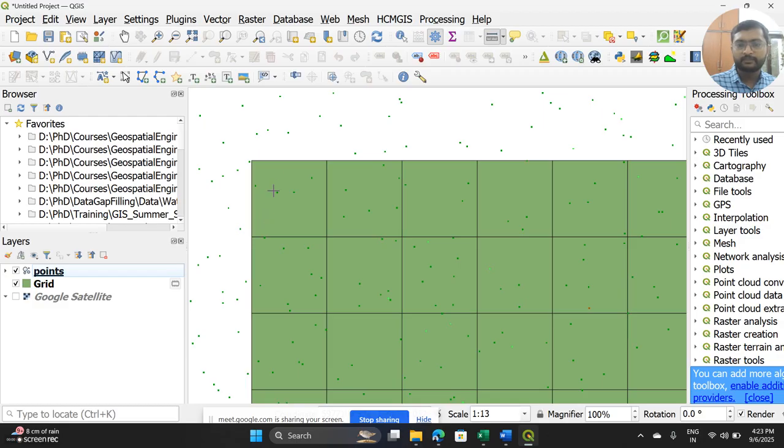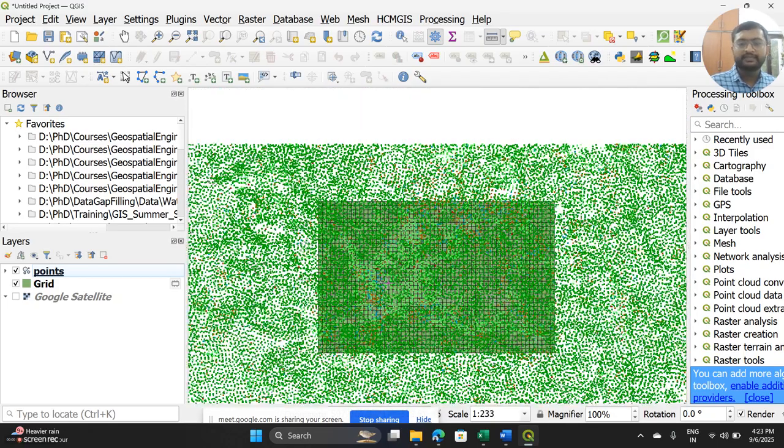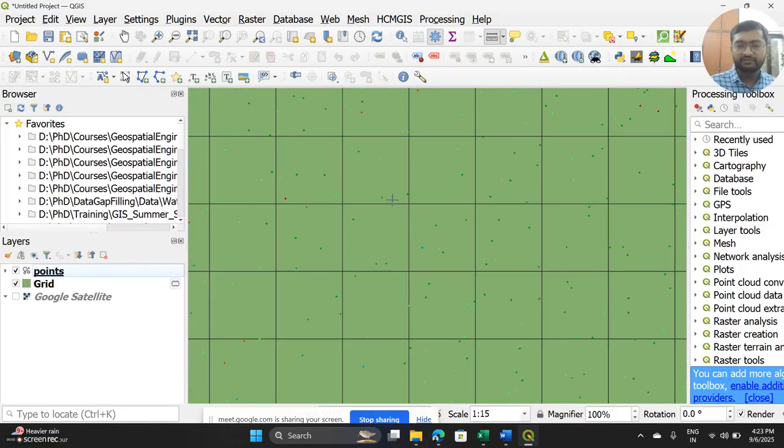Did you get my point? I will take the mean elevation value of all the points which are coming in this grid. Okay. Yes, sir. Similarly, I will do it for all the grids, and I will generate continuous data. So basically, if you have a variation within the grid only, you might not be able to represent the surface well. But this is how the data is being created. You have to specify some dimension to it, and then you have to do interpolation.